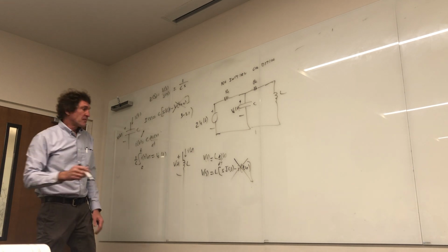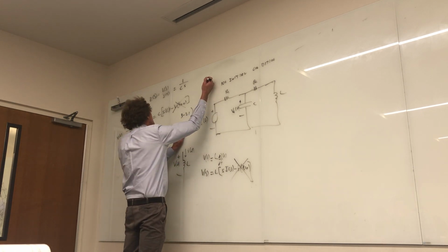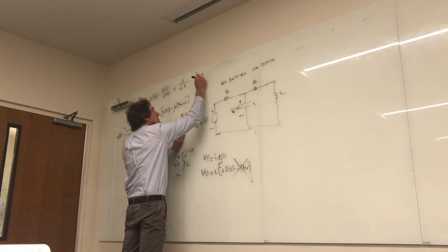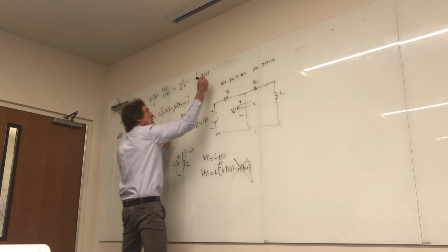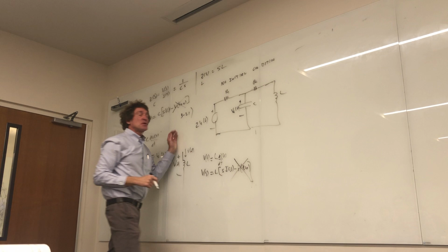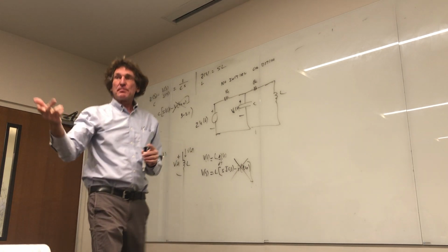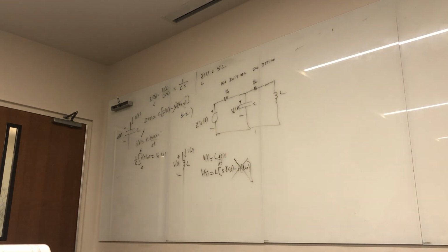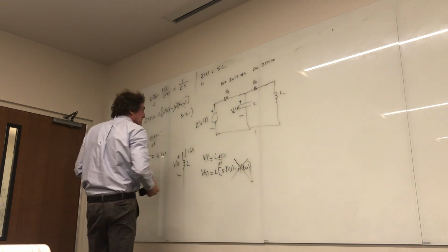And if that goes away, furthermore, if I look at voltage over current for an inductor, I would have Z of S, and this would be for an inductor, this is for a capacitor, equal to SL. So now you're seeing that the relationships are exactly parallel to what you did in your circuits courses if there are no initial conditions. I'll get to things where there are initial conditions in a bit. But first, this is the most common thing you see.